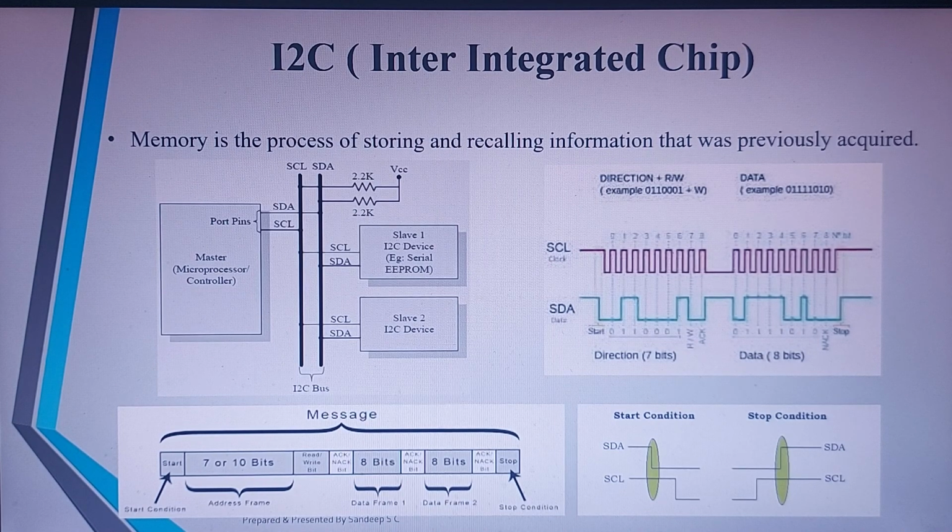So in this type of communication, if you see the next block, you can see a clock signal, SCL, and SDA data, how the digital signal is varying depending on the information bit, whether it's 0 or 1. Whatever data has to be sent, when the clock is high, the data status should not change. The protocol should make sure that whenever the clock is at logic high or logic 1, the status of the data signal should not change. The data will change from 0 to 1 or 1 to 0 only when the clock is logic low.